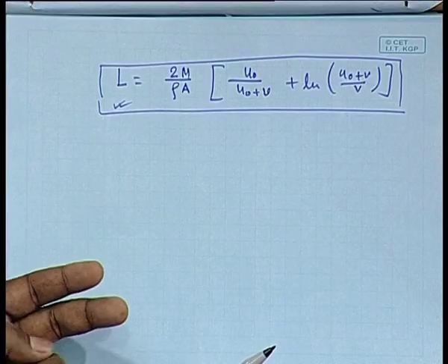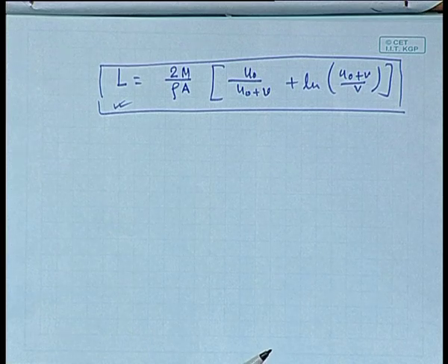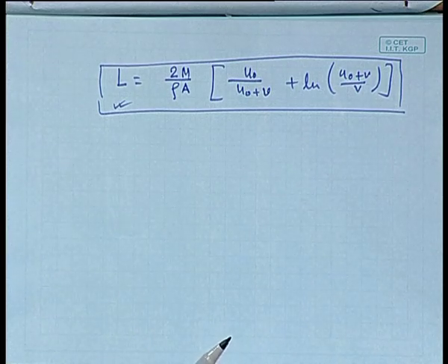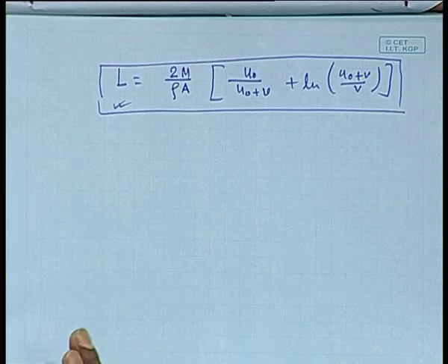Now what you have to do, basically you have to put a y component equation of motion and write down the y component momentum balance. Okay, and since the fuel is coming out at a constant rate 5 kg per second, you have to do a material balance as well to find out whatever mass is remaining in the rocket at any point of time. Now whenever you are compiling the y component equation of motion, the mass will be the mass of the control volume remaining at time t, which you will obtain from the material balance. Then you have to integrate.